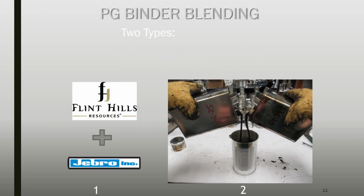So what happens when the contractor has to switch binders during the project and only has one tank? This is called PG binder blending. There are 2 types. The first one is when they blend 2 different suppliers, and the second is when they blend 2 different grades.